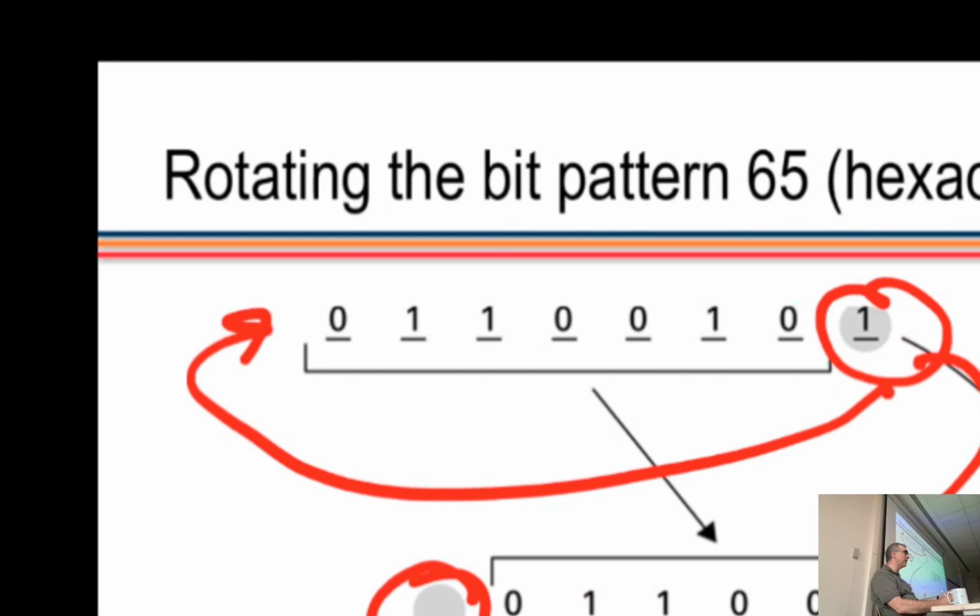You are trying to read that switch. So you may need to rotate left 1, 2, 3, 4, 5 times and check the sign of the number. If the number is negative, then that bit is 1. If the number is positive, that bit is 0. So that is one thing to reach that.